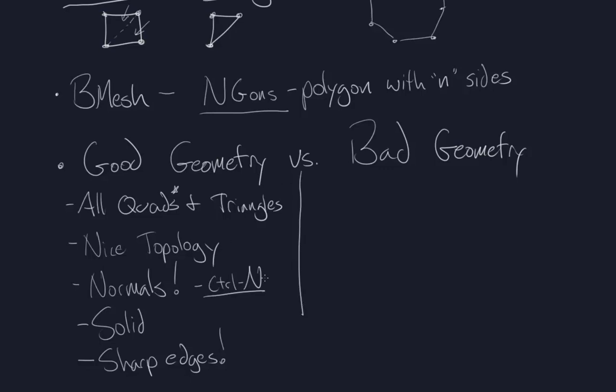Now, that being said, this is one of those steps I would definitely save for last. Because if you just go one by one through all of your hard edges and you use, say, the bevel tool or whatever operation you want to use to make those a little bit more rounded, that's great, but then if you need to go back in and do further modeling, you'll just find that you have a lot more geometry to work with than you really need.